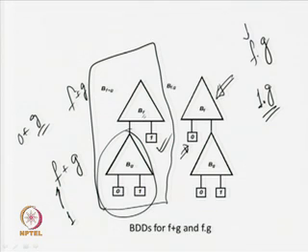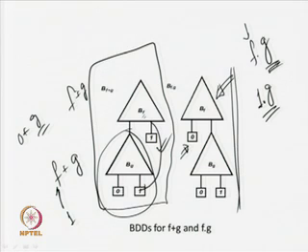If f is 1, then what happens? I am going to look for the value of g. So I will simply plug in the BDD of BG for function g in the one terminal nodes of this particular BF, and eventually it is going to give me this. And later, since these two can be merged, I can redirect this one to these things, and I can redirect this one to this. Again, after having these two BDDs, we are getting a BDD. If required, I can go for reduction of these BDDs also.